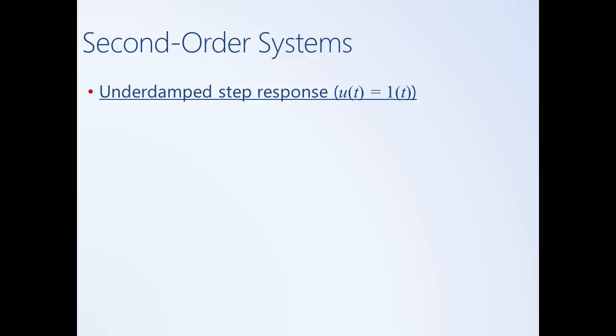At this point, we're now going to derive the equation for the step response of an underdamped second-order system. And just as was the case with the first-order system, we'll show longhand how to find this response, doing partial fraction expansions, using inverse Laplace transform, but then we won't do it ever again. This standard response is common enough that we're just going to memorize the character of it.